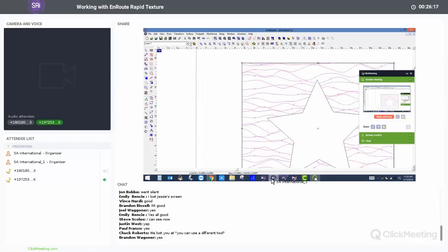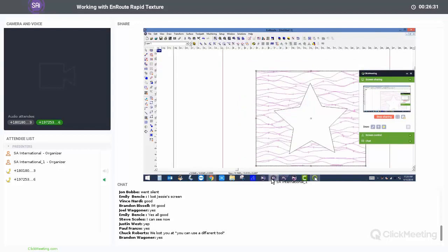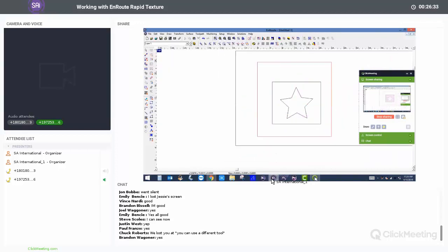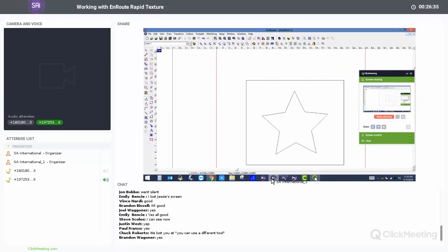Now there are a couple little tips and tricks along the way with using masking. For instance, if you're using a 90-degree conic to do your texture and your cleanup as well, you would create a 1/8" offset if you're cutting 1/8" into your material. So depending on how deep you want to cut is going to be how big your offset is going to be.